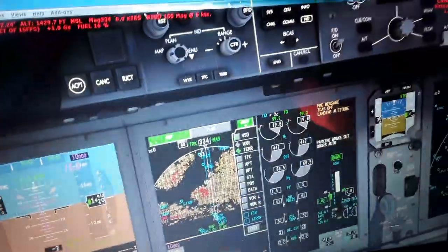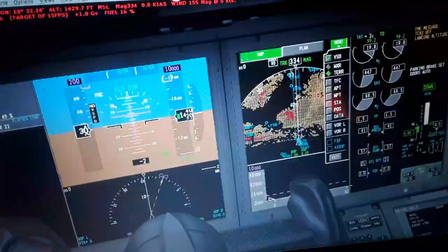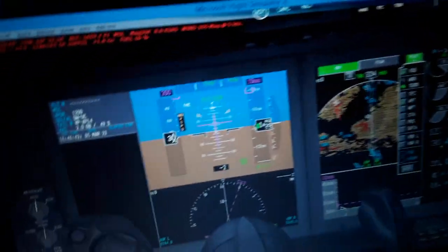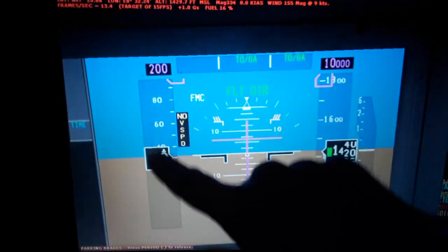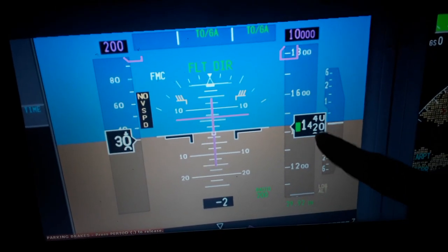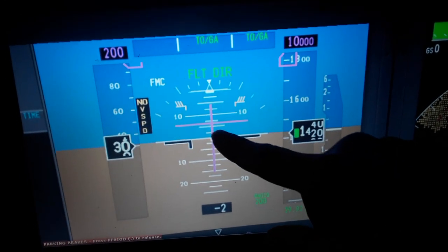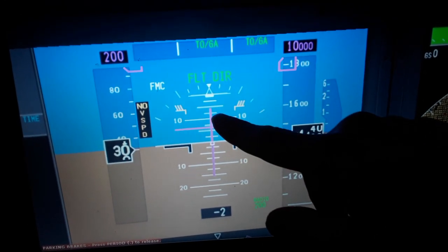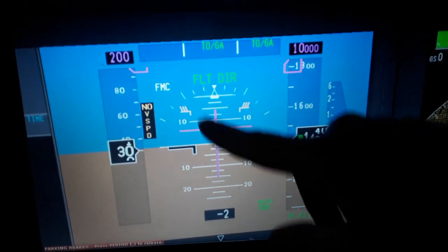We have also other displays to show you later as we go on before a flight. So we have also to see here, you can see the airspeed indicated from the pitot dynamic and also the altitude, pitot static and pitot dynamic tubes, vertical rate of climb descent, pitch attitude 2.5, 5, 7.5, 10, 12.5, 15, 17.5 degrees, pitch up and pitch down.